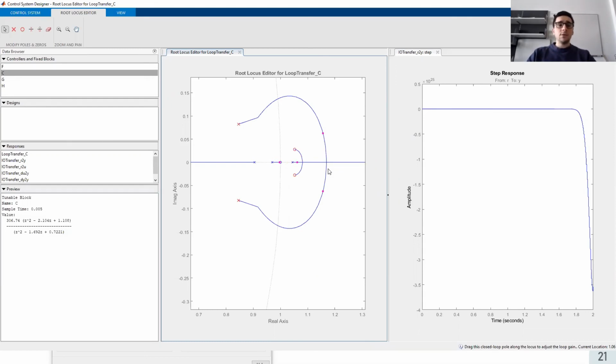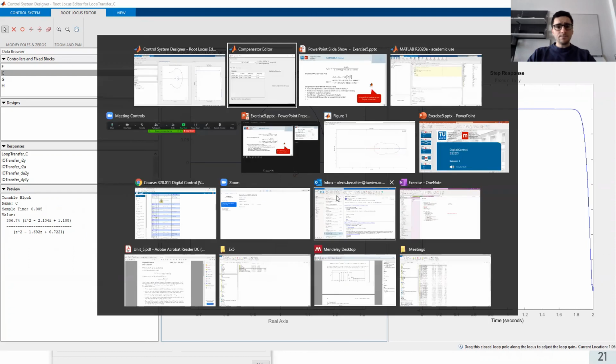You can add as many zeros, as many poles as you want, but still it can be quite tricky sometimes to find all the closed loop poles being stable, and to have a controller here that is feasible. So same number of poles and zeros or more poles than zeros, that have a step response that is stable and probably not reaching zero, for example. And so even if this is really powerful, it can be really tricky to use.